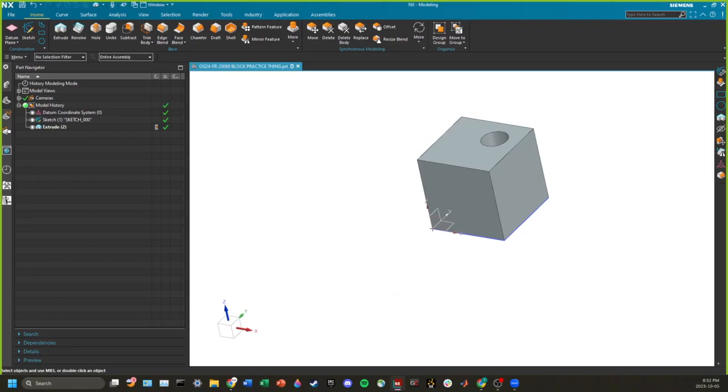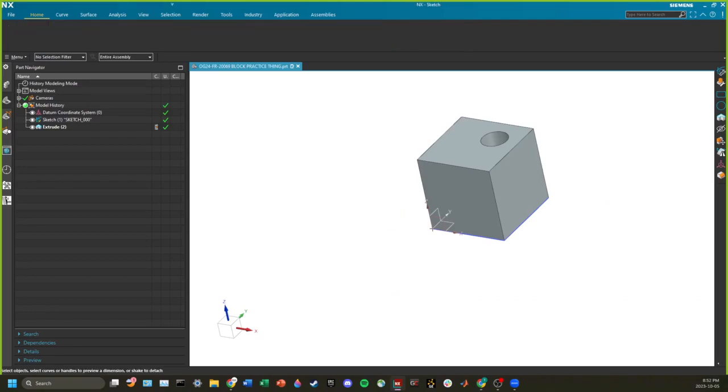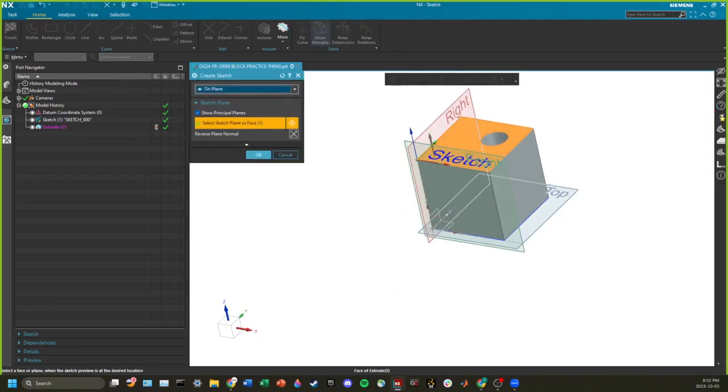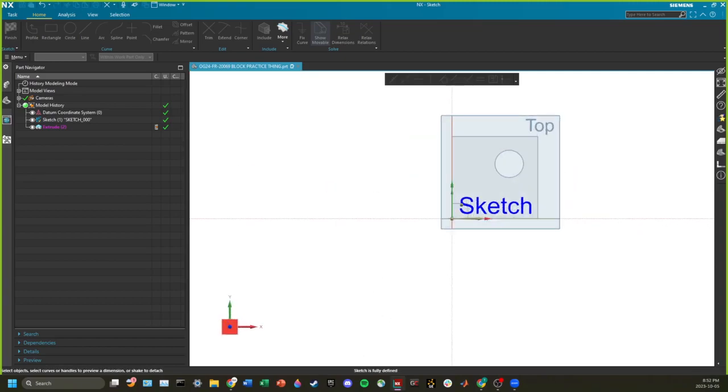Let's do that. If I go sketch, I'll click the front plane. I'll choose this corner. If you go over here or here or here, when you click, you'll see that the origin is around, right? I'm going to choose it right here because that's where I want to put that bite out of the cube. Okay.